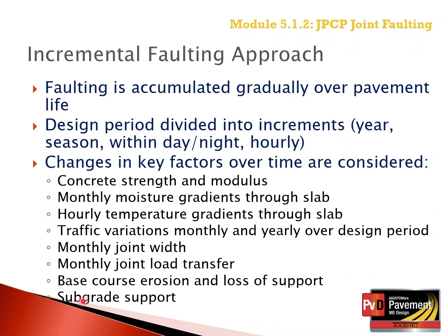In summary, faulting is accumulated over the design period. The design period is divided into time increments, and the changes to the pavement and site factors are determined for the specific time increment. The pavement and site factors considered within each increment include the concrete flexural strength and elastic modulus, moisture gradients throughout the slab,